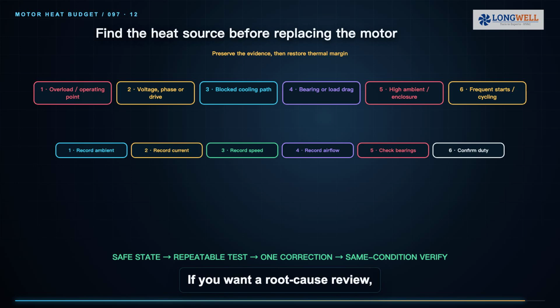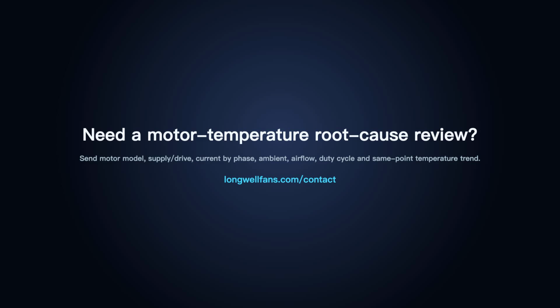If you want a root cause review, send the motor model, supply or drive, current by phase, ambient, airflow, duty cycle, and temperature trend.